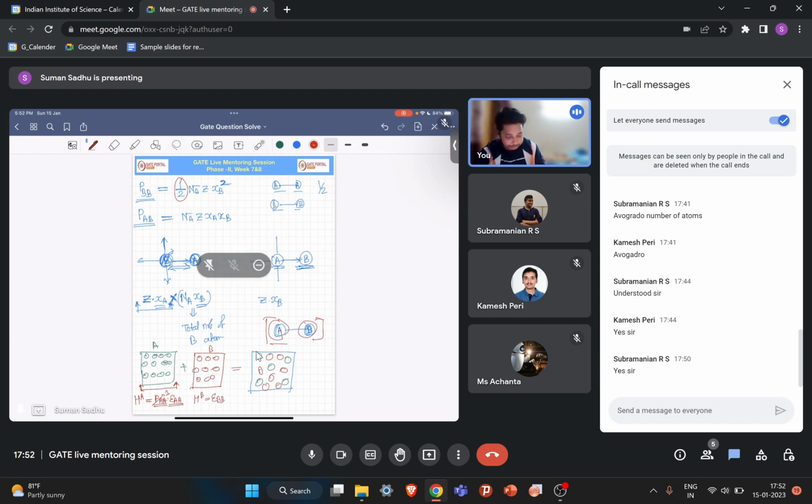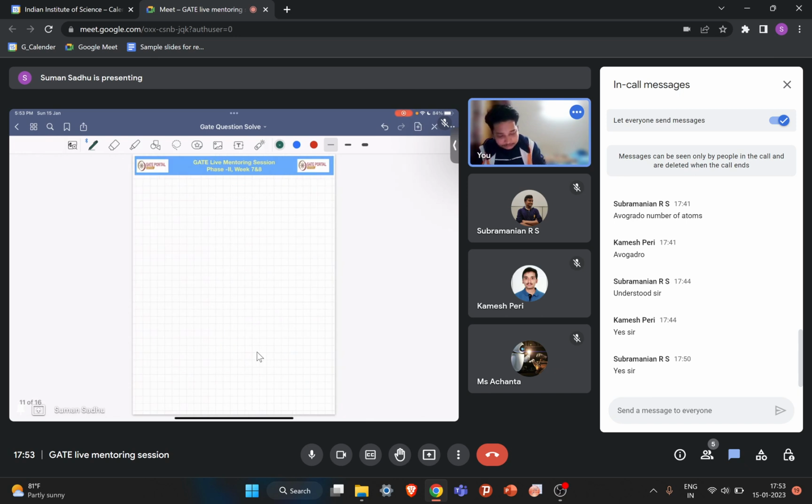But when the solution is forming, you have three types of bonds: AA type, BB type, and AB type, and we have already found out the probabilities. So in this case, your H of solution is equal to P of AA epsilon AA plus P of BB epsilon BB plus P of AB epsilon AB. Then what is the enthalpy change when the solution is forming? The enthalpy change is delta H of mixing. We can write it as H of solution minus H of A plus H of B, right?